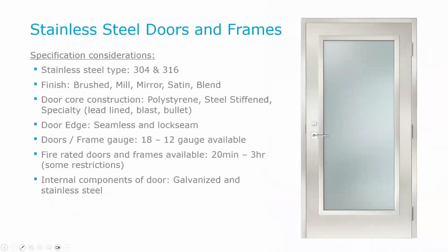So within stainless steel, we have 2 different types of steel that you will see day in and day out, and that's the 304 and the 316. For most types of projects, 304 stainless steel is just fine. 316 is where you will see it required on wastewater treatment facilities. As I said, in food processing plants, their standard is the 316. The 316 basically is a steel that has more chromium in it to make it more highly corrosion resistant. So especially on wastewater treatment facilities or chemical storage facilities, you may see it required to have a 316 steel.